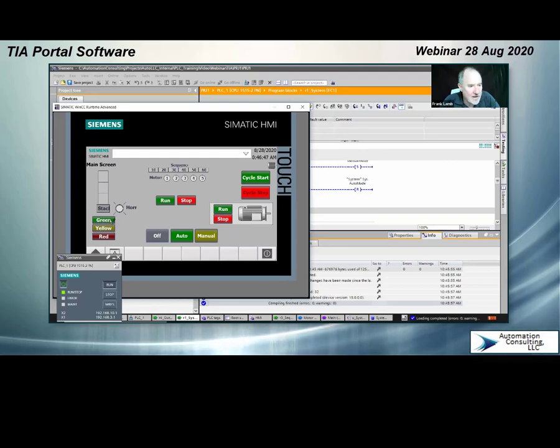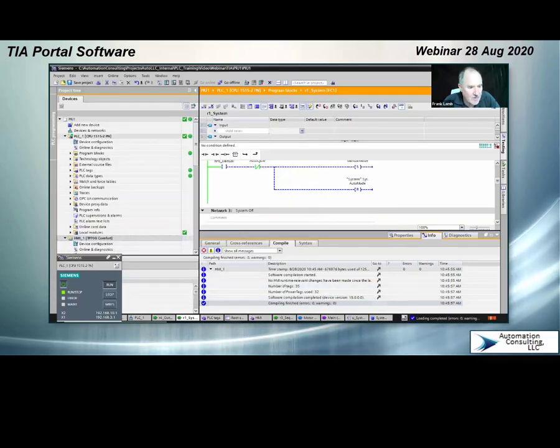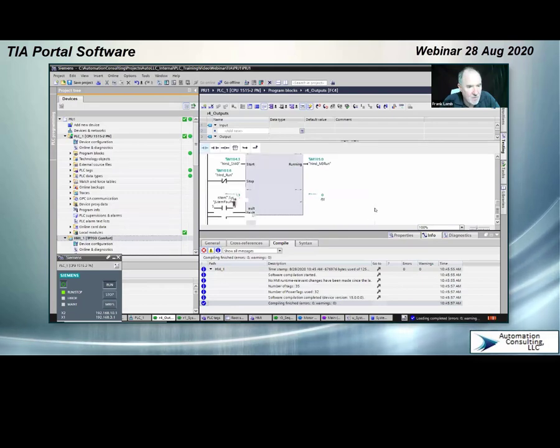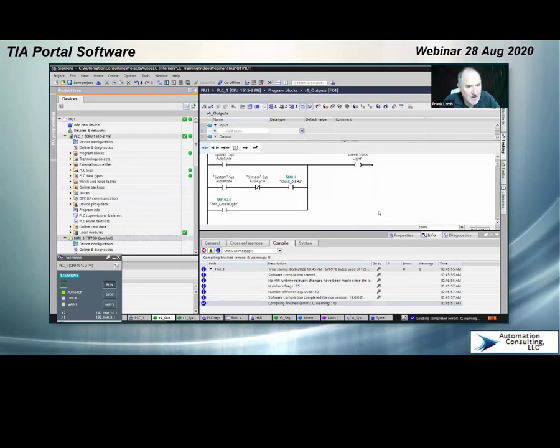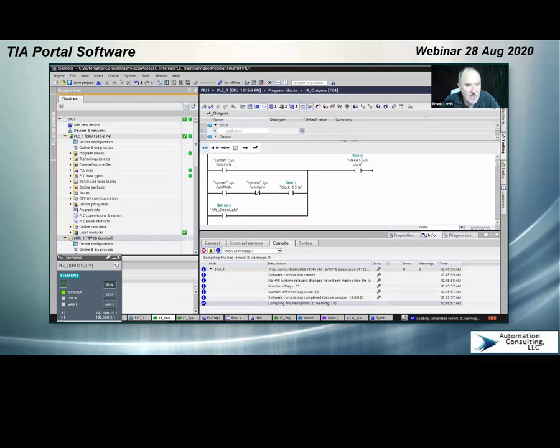And what I did is I created some buttons that actually turn on the lights. So the first thing I did if I wanted to simulate things is go into the outputs. That's where I like to put them. And this is where some of the logic is for the stack light. I didn't use any real I/O here, but I did imitate real I/O with the stack light. So you can see if I'm in auto cycle, my stack light's on permanently green. If I'm in auto mode, then that internal clock blinks and it blinks the stack light.